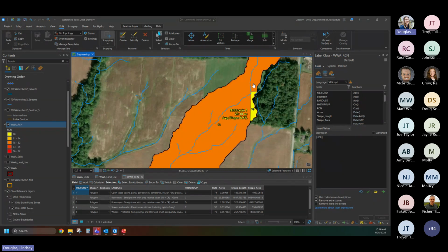Luckily, the end portion is very similar to the previous tools. It's just that project setup. That's the big difference, and really that DEM step and remembering what number goes in here. And of course, it's got a glitch too with not wanting to merge multiple DEMs. If you do try to use it and you have multiple DEMs hoping that it will combine them, it will just throw an error and say that the mosaic to new raster step failed.